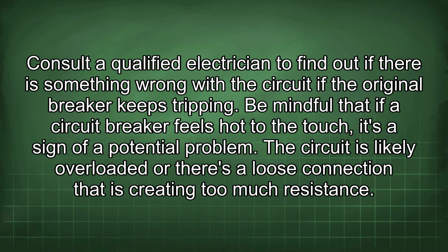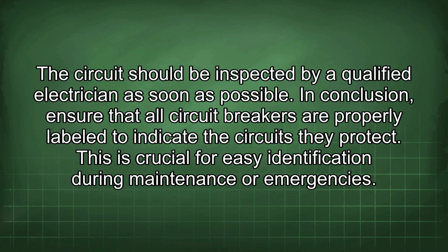Be mindful that if a circuit breaker feels hot to the touch, it's a sign of a potential problem. The circuit is likely overloaded or there's a loose connection that is creating too much resistance. The circuit should be inspected by a qualified electrician as soon as possible. In conclusion, ensure that all circuit breakers are properly labeled to indicate the circuits they protect. This is crucial for easy identification during maintenance or emergencies.